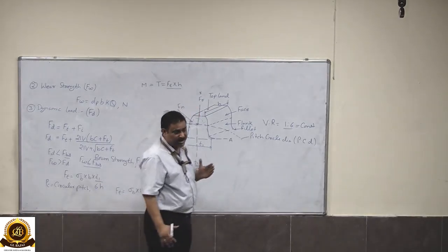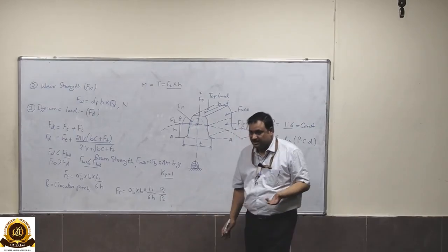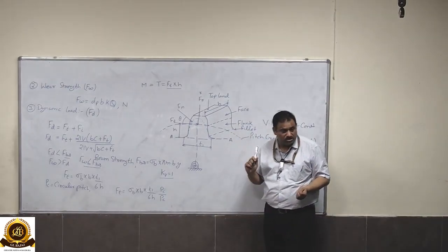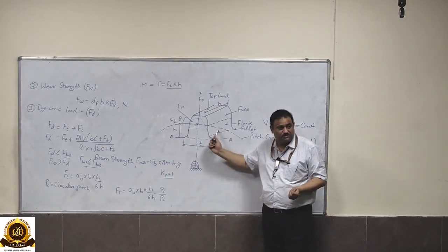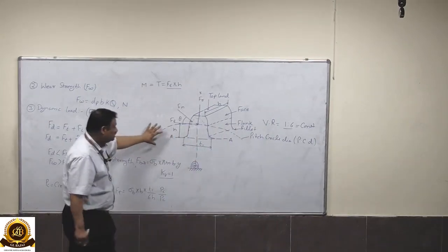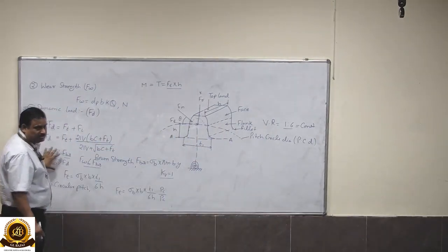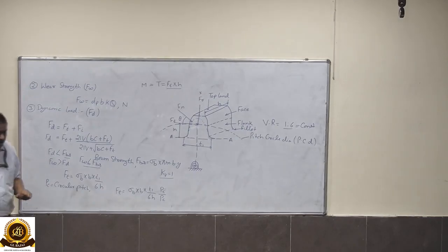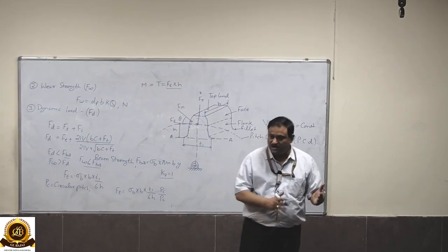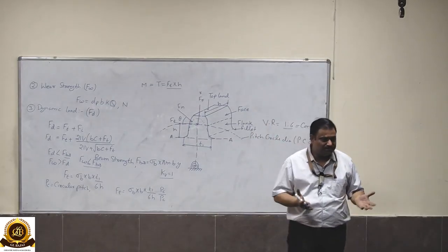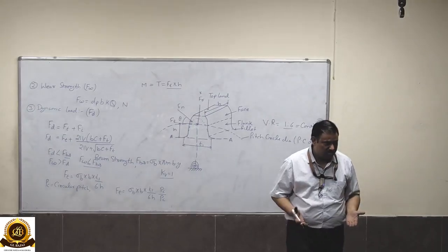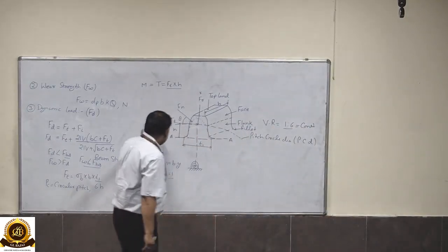So in order to check the sufficient wear strength, whether the gear is safe in wear load, we have to just calculate the BHN value, Brinell hardness number, and this BHN value will satisfy the requirement. Okay, this is a standard procedure which can be adopted for any type of gear, whether we design a helical gear, worm gear, or bevel gear. Okay, so next is